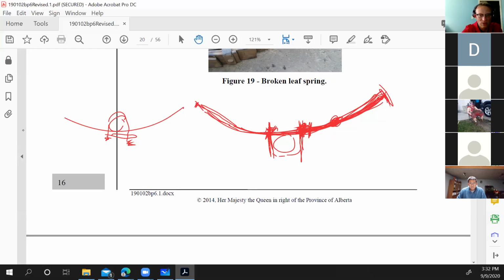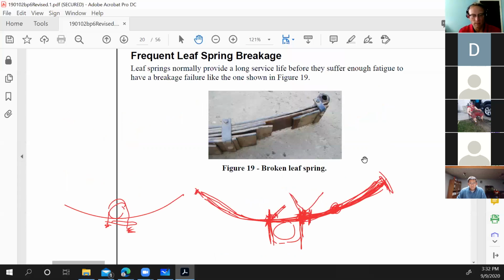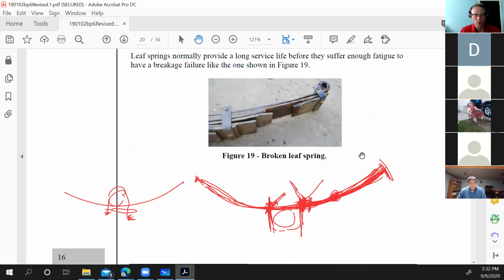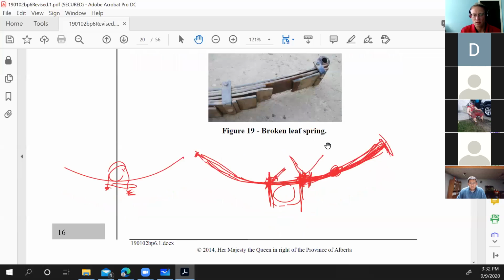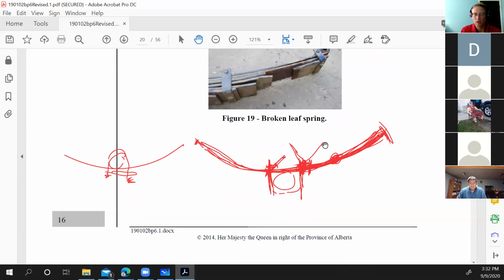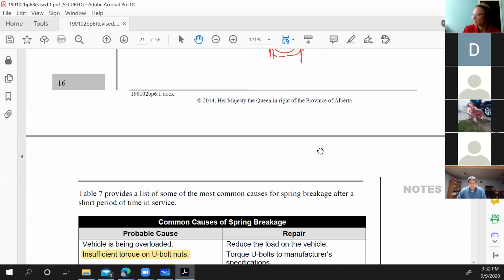So this is able to move and it's only held still here. If the whole U-bolt side goes loose, it's going to break very quickly. It'll just flap around and break very quickly. So it's not necessarily that it'll cause work hardening, it'll overload it, and that's how it'll break, I guess, which will eventually cause work hardening if it stretches or starts bending beyond its yield point.